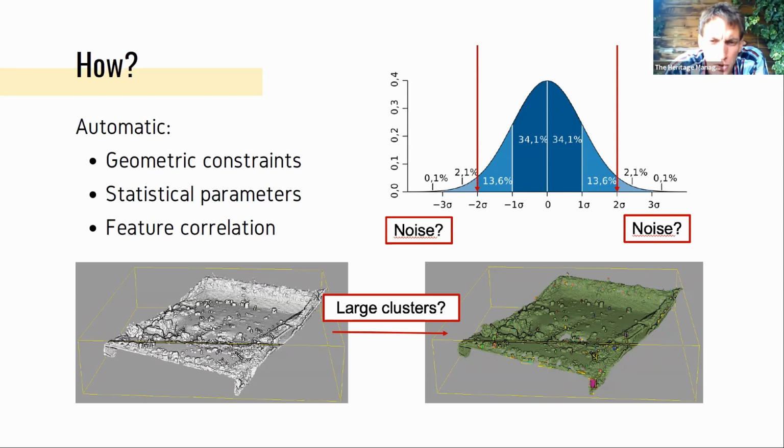If you're more involved in statistics, there are different approaches that you can use, but only one, unfortunately, is implemented in Cloud Compare. So we will only use the standard deviation related to the mean of our elevation value. But of course, there are other statistical approaches that you can apply here, and I will end with that at the end of this presentation.